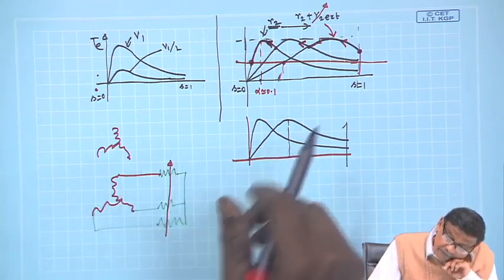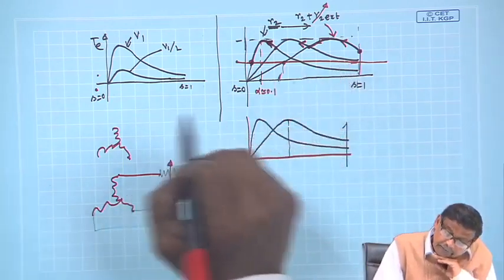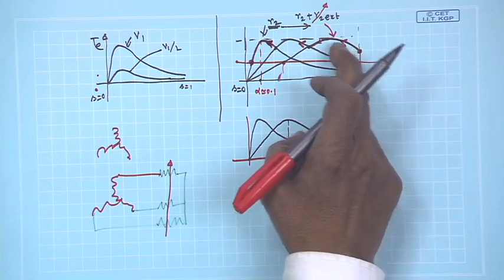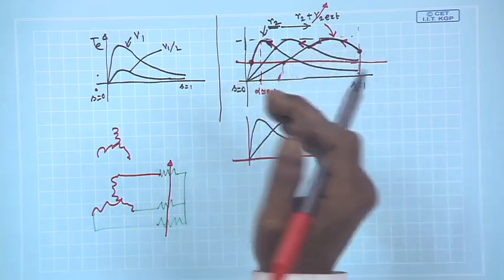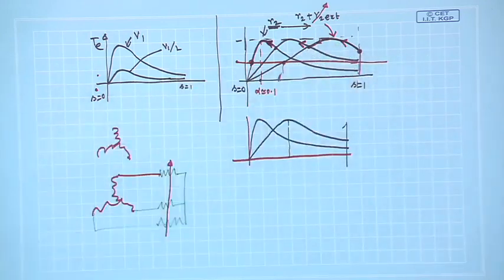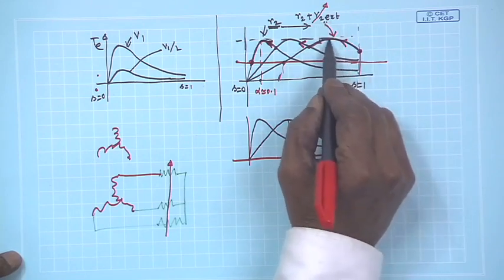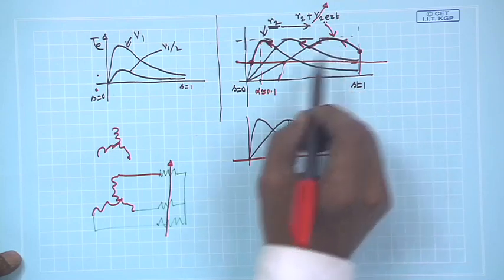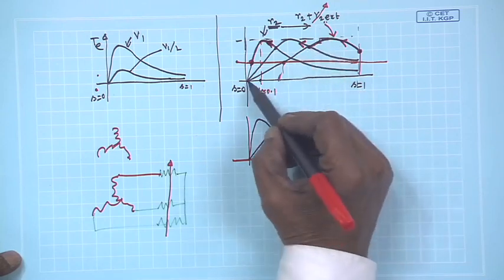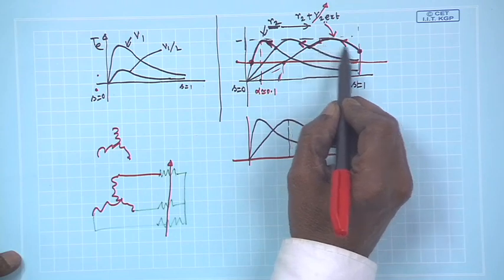That is, you should always think that this external resistance is to be cut out, and how the operating point will move. You come here, you decrease this resistance, and some torque slip characteristics based on the R2 external exist.